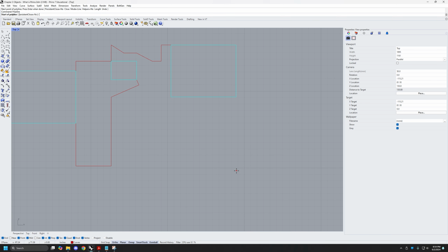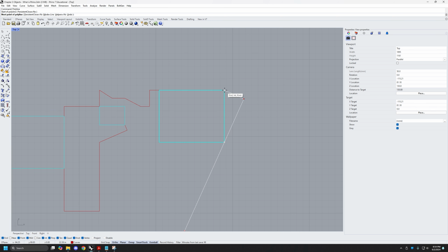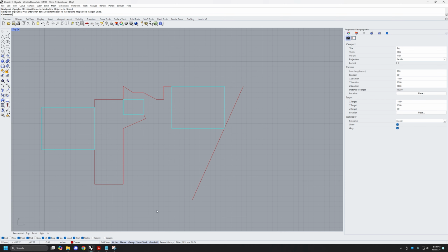Again, that tab constraint can be created kind of wherever you start. So this is polyline again, just starting a first point. Maybe I need to snap to this point, get that gray Smart Track feature, press tab, lock it in place. And then I could extend that and maybe get this corner here. And maybe my line needs to stop at that point right there. So I bring it over to the intersection, click, and then press enter to finish. So there's a way to really precisely create basic geometry. It's just all using polyline, but it's able to reference those precisely and accurately.